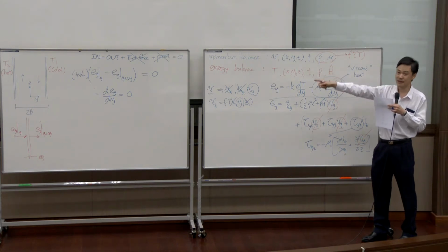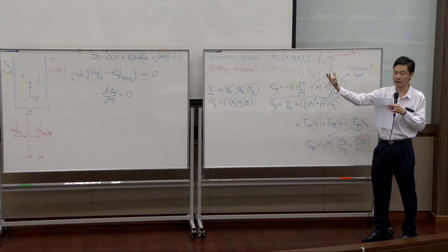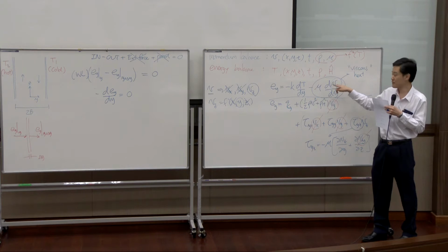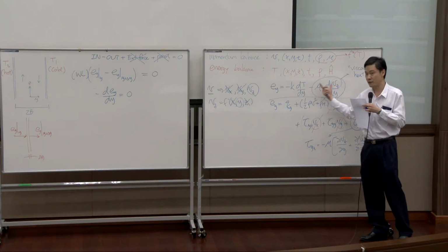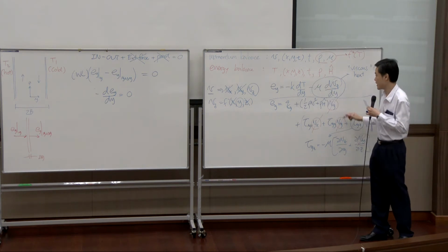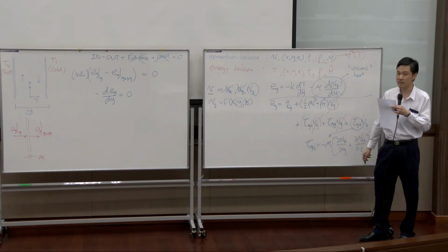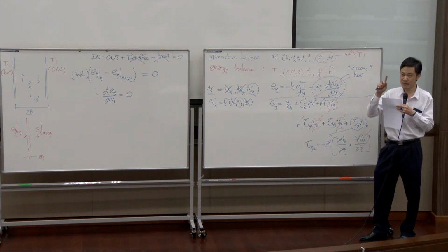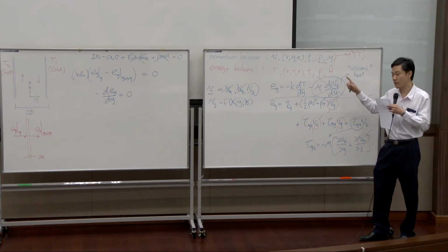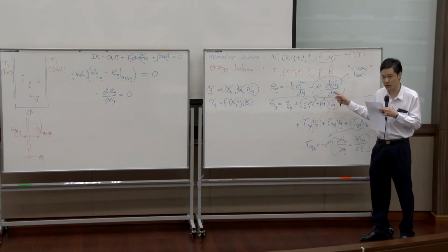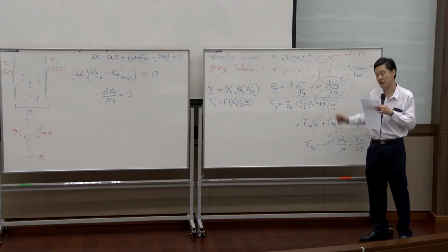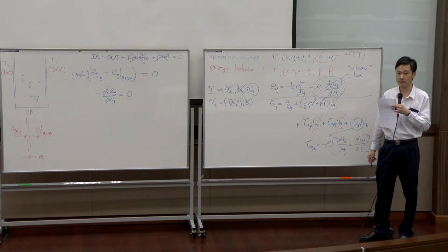In this case, it is natural convection. Fluid is moving slowly by means of difference in density. So velocity is so slow. Viscosity is not significantly large because we talk about regular fluid. So comparing conduction and viscous heat for this example, we can say that the viscous heat term can be neglected. Please keep in mind, we are not neglecting the velocity term. We just said that velocity is so low, the flow work term is not comparable to the conduction term. Okay?